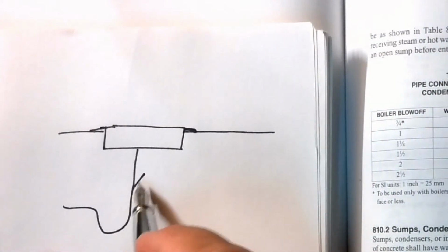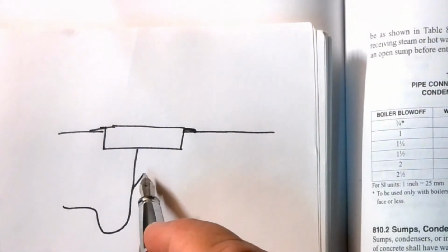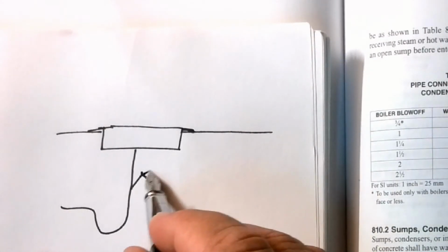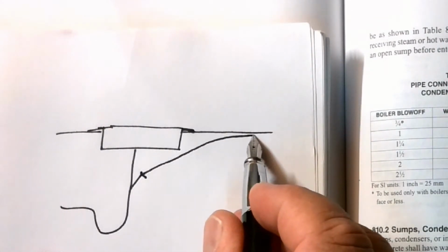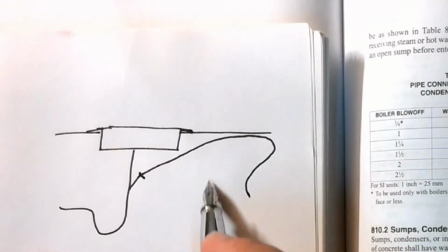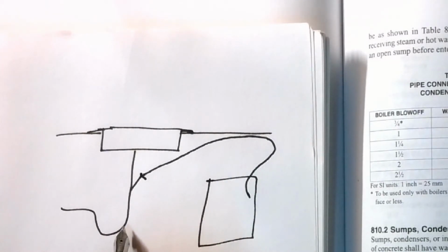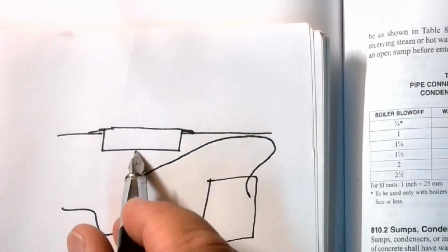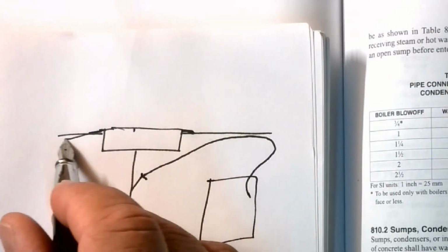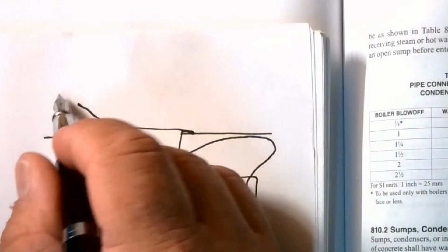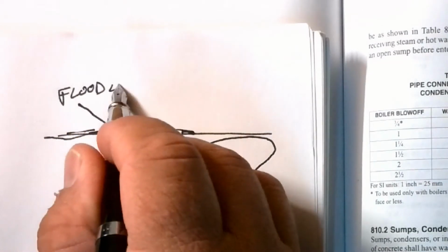So they put in a Y branch tailpiece right here and they're going to hook this hose up. At this point, they run a hose, and what they do is they run the hose as high as they can and then hook it into your dishwasher over here. If there's ever a sewage backup, where's the sewage going to go? It's going to come through this trap, come up through here, and want to go all the way up to the sink and overflow out over the, what's this called right here? The flood level rim, right?